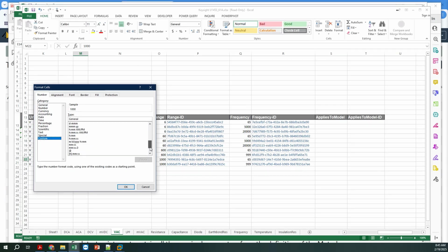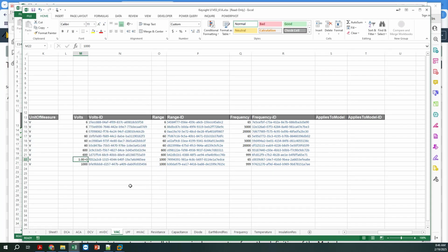And then here we've added in some custom formatters. So this right here is going to move it to scientific or to engineering notation. So it will put it in as a 1E3, but that engineering notation doesn't cover enough resolution.